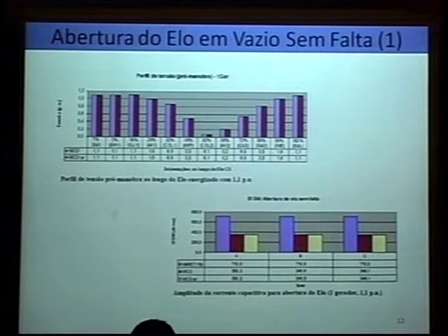So with the decrease of voltage in the middle of the line, here I'm comparing cases with and without surge arrestor. It was expected for the surge arrestor not to work in this case. And on this other graph, I present the capacitive current that was interrupted by the circuit breaker. The standard establishes for the opening of the circuit breaker a current of 710 effective amperes, and the current obtained for the half wavelength line was way below the established current by the standard.